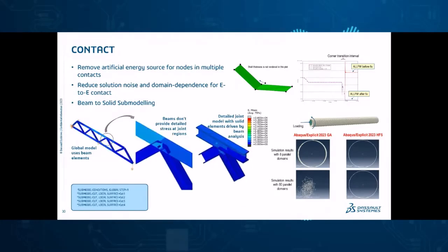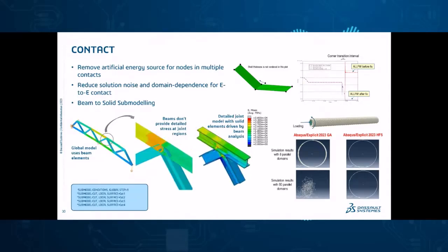Solid element submodels can now be driven with a global analysis using beam elements. And along with this functionality, there is also a simplified keyword interface, and that includes the specifying of the local cuts, and these being driven by distributed couplings.